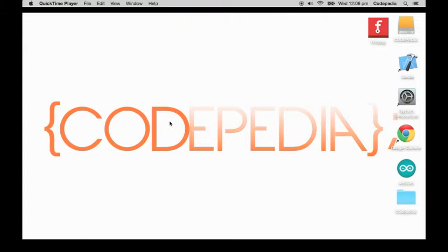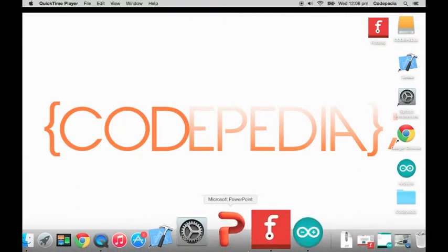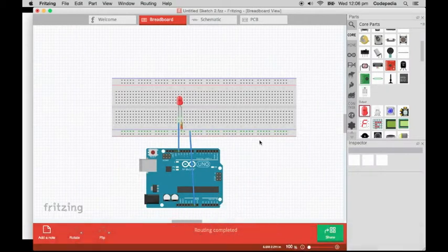First we need to look at how to wire up our project. As you can see on this diagram, you'll place an LED into the breadboard and have the negative end, the cathode, connected to a resistor into this row here, which runs horizontally.